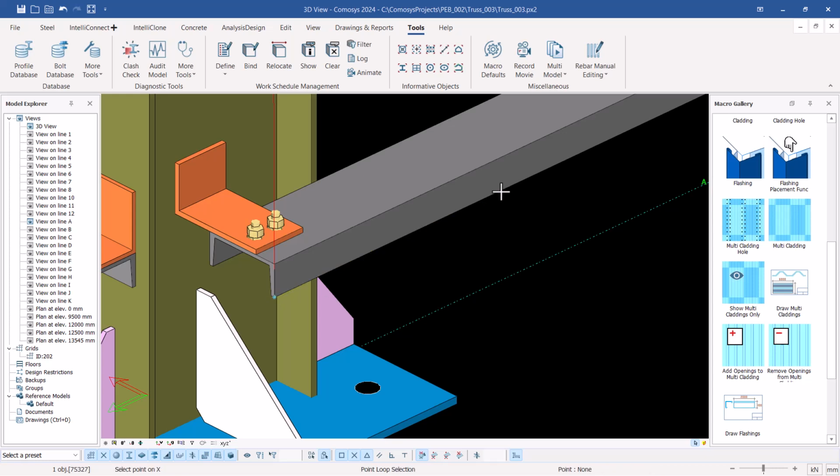So I'll just press Control and snap on any location here. Let me just snap on that spot, and once I've snapped on that spot, just by clicking on X, Y, you are defining the arrangement of how you want the sheets to be arranged.